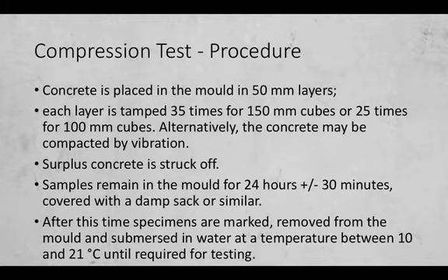So you submerge it in water, meaning you put it completely in water until ready for testing. And you have different day lengths when you want to test concrete. You have 3-day tests, 7-day tests, 14-day tests, and 28-day tests. So these are different days.